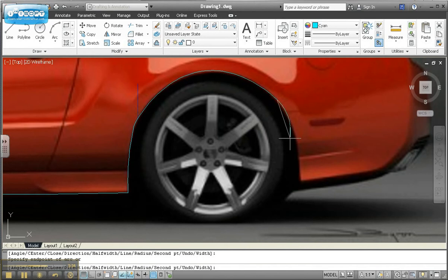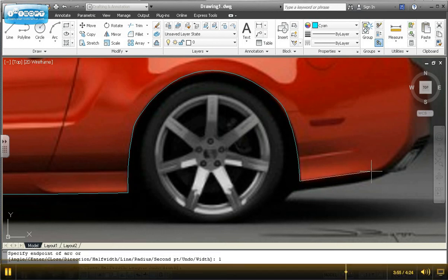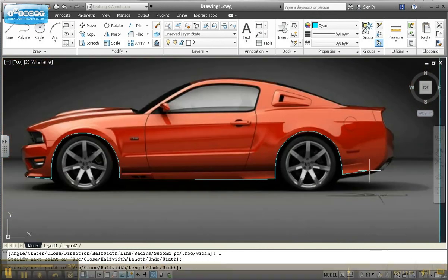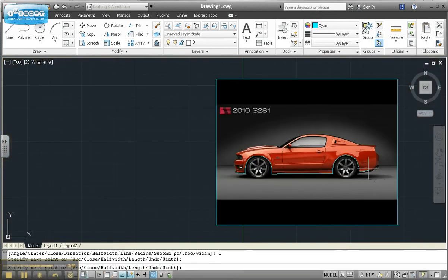And again, if you mess up at any point, like say this curve, I go over here, whoops, wrong click, hit Control Z, and that will undo whatever you just did on your keyboard. There we go. Alright. So now again, if you want to switch to a straight line, it's L, enter, and then you get back to your straight line. And at the end, let's pretend I'm done here. I hit enter to end my P line.